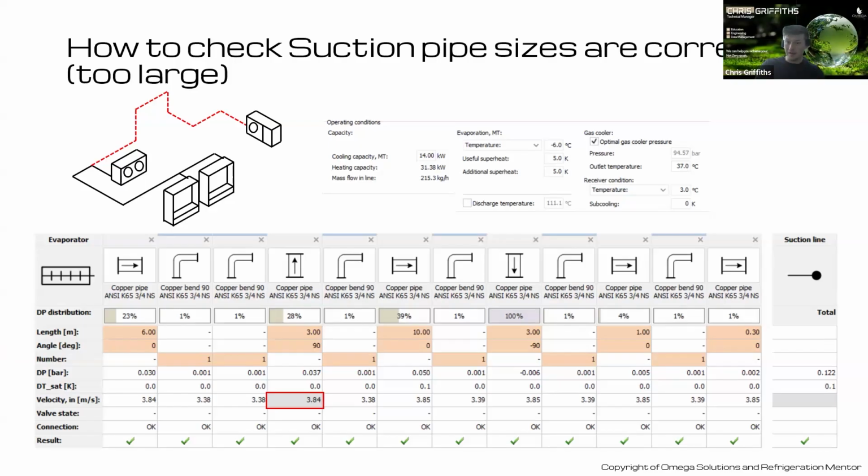Yeah. Just before we move on as well, vertical height from the evaporator to compressor is more than 4 meters. Is a U-trap sufficient or must use double riser? Neither. So put a U-trap in anyway, because it's important for that oil to be able to build up at part load conditions until the pressure behind it is enough to force it up the trap. And also you don't want it then running backwards, potentially back into your evaporators. We've managed to get it up out of the evaporators to the base of the riser anyway. We don't want to undo any work that the system's already done to do that. So we end up putting that trap in.